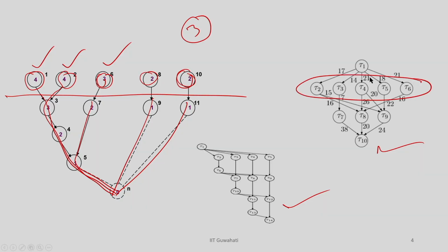This may not give you the optimal solution in some corner cases, but most of the time this is a logical assumption, even for a sequence graph, which is a graph, not a tree. Among the operations available to be scheduled, I am going to take the operations which have a higher level. For example, in this example, suppose these nodes are available to be scheduled in time step 1,